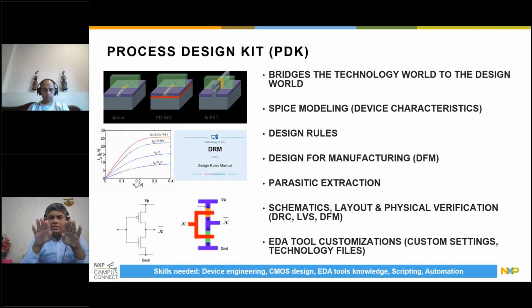When you lay those out, there are various levels of masks, whether they are front-end layers like active layers, poly and contacts, or metallization layers from metal 1, metal 2, metal 3, up to metal 7, like a stack, with the vias in between. Now these, you cannot just lay them out like anything. Like any discipline, there are rules, because if you're drawing two wires, you cannot come too close, because there will be some interference and some spillovers or fabrication mismatches, and they get a short. At the same time, they should be at a certain distance so that they are yield friendly. So there are design rules.